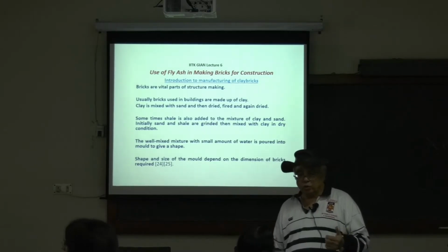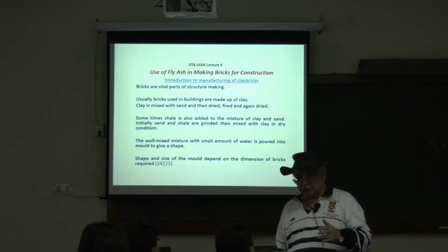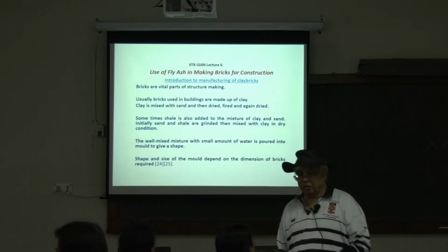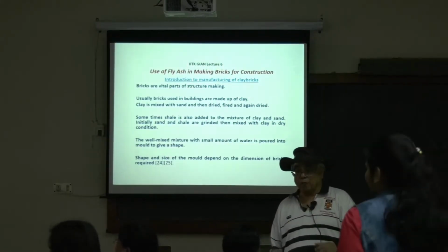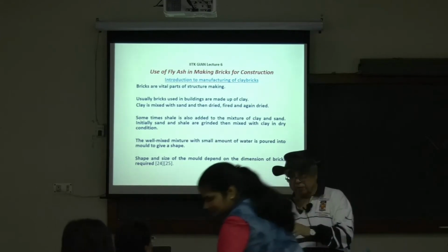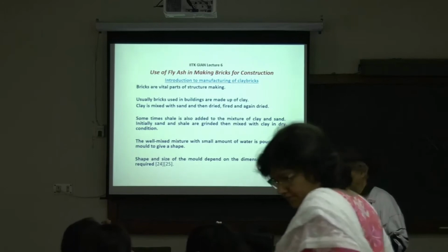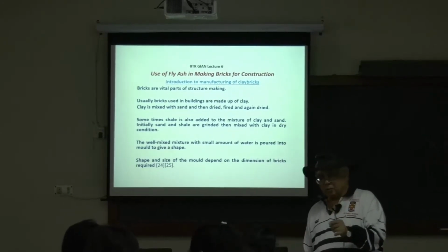The ones which you showed, one fly ash had about 100 micron particle size, but the rest of the fly ash had particle size about 10 to 15 microns. One you have mentioned there is 45 microns. 45 microns, so those which are 10 to 15 microns, they are much useful. It is generally spherical, but there are some which are little bit spherical.